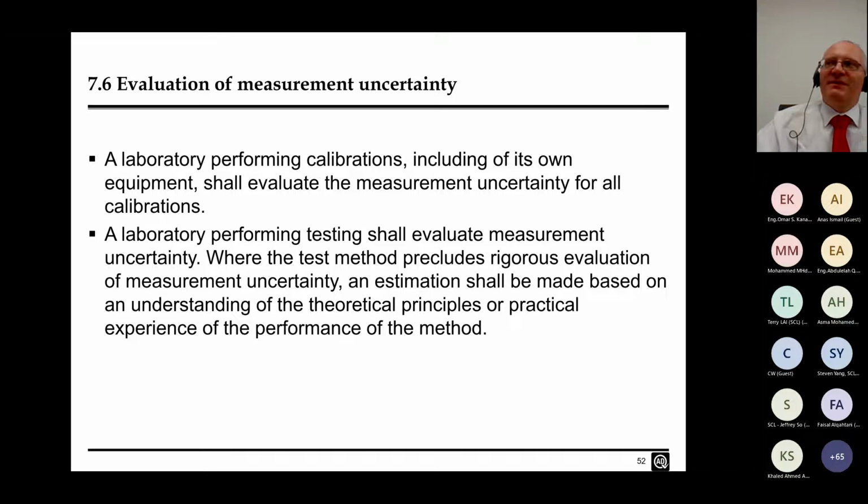Measurement uncertainty. And again, I'm not going to talk a great deal about measurement uncertainty because I'm sure that Omar is arranging a whole talk on the subject. But what do we know? A laboratory performing calibrations, including for your own equipment, shall evaluate the measurement uncertainty for all calibrations. This is not something that's always done by the commercial laboratories. When they're claiming they're out of accreditation, they quite often send out certificates without measurement uncertainties. I'm sure you don't do that.